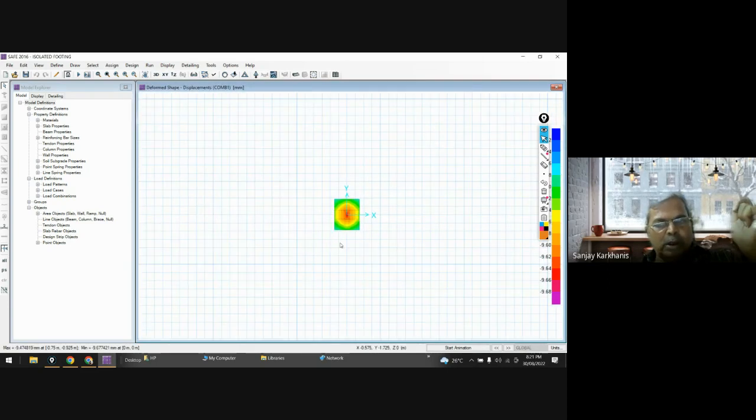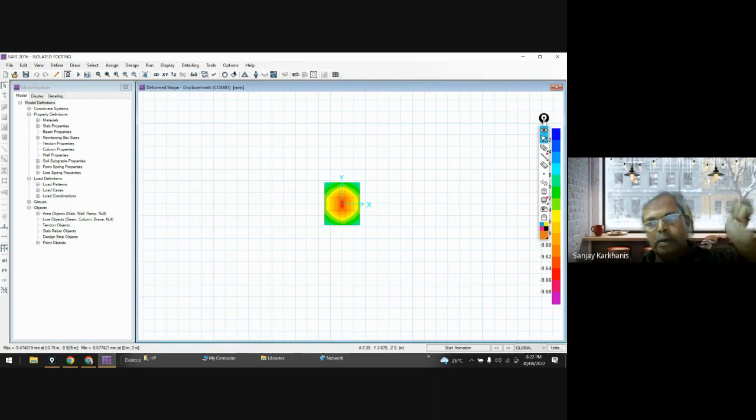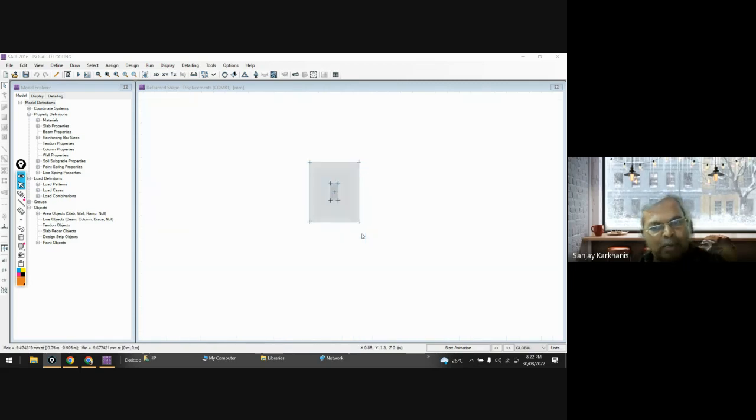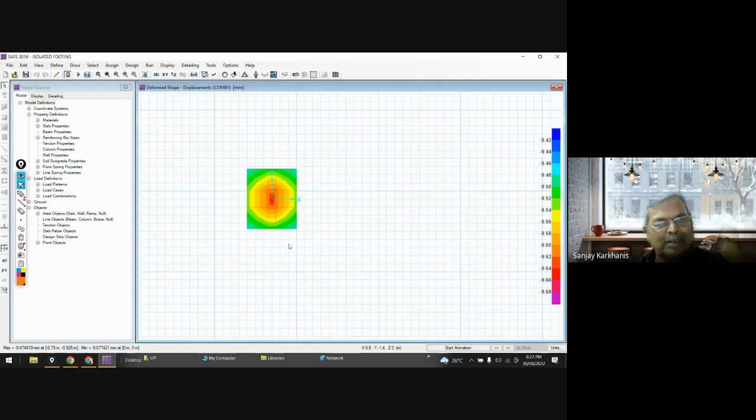Now you will see, sir, is there something or not? See, it has given you the pattern, and you can see for isolated loading conditions, the pattern will be just like this, because a settlement will be heaviest at the center point because there is only one point, and the remaining part is cantilevered. So the settlement will always be heavier below the column, and you can see here a bar chart, or you can see classification.